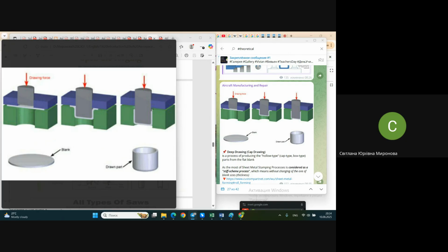While drawing, there is a piece which is not changed at all, a never-spoiled element. Here is the bottom that is under the punch. Typically, this bottom is without a hole. It may have some little hole, but typically it's without one. If it's necessary to make a hole here, typically it's made after the drawing operation. And this bottom is the only element that is not spoiled.